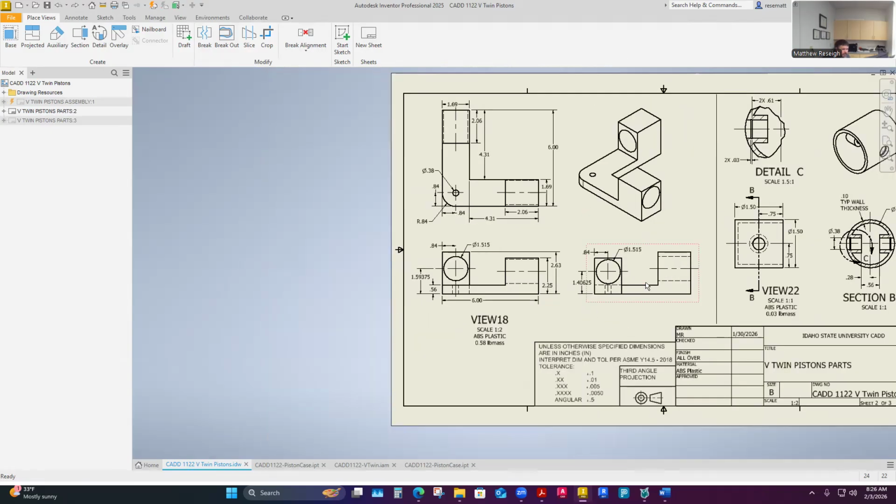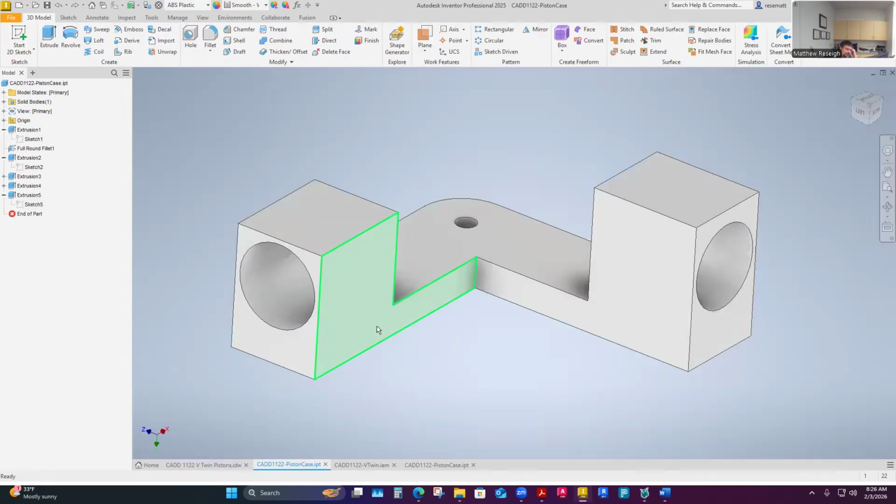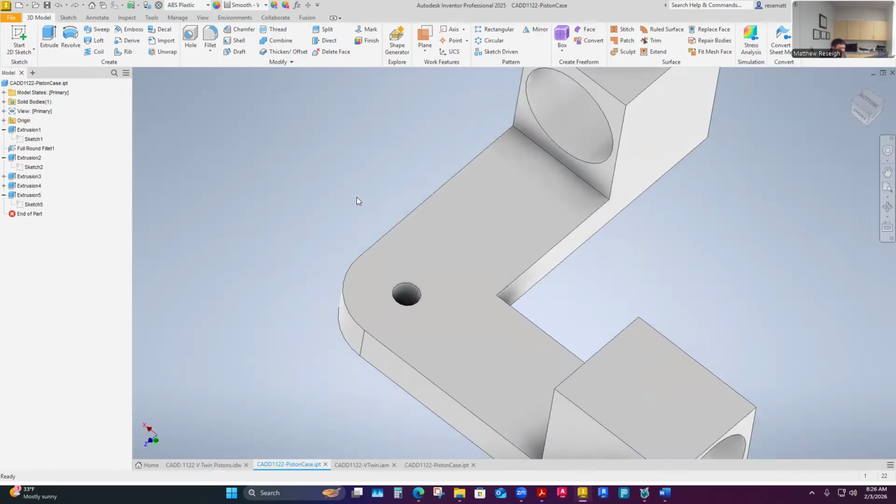And the only ones I really changed on this were those two dimensions. And I'm going to change this hole as well. I think I need to tolerance that hole. So I really have just added some extra careful dimensions to the through bore and their heights where they're aligned. Maybe that's my most critical stuff, except for the hole as well, which is this hole. I think I told you to go out 10 thousandths on these. Let's just see if I was right.